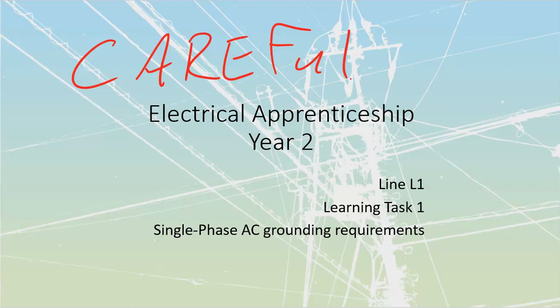So the very first one that they talk about is going to be sizing, and sizing of the ground conductor itself. Now the ground conductor, if you watched that review video, we took a look at fault current that is going to be traveling along the bonding pathway. The ground conductor carries little to no current ever. Practically speaking, it could be as small as a number 14 or a number 16.